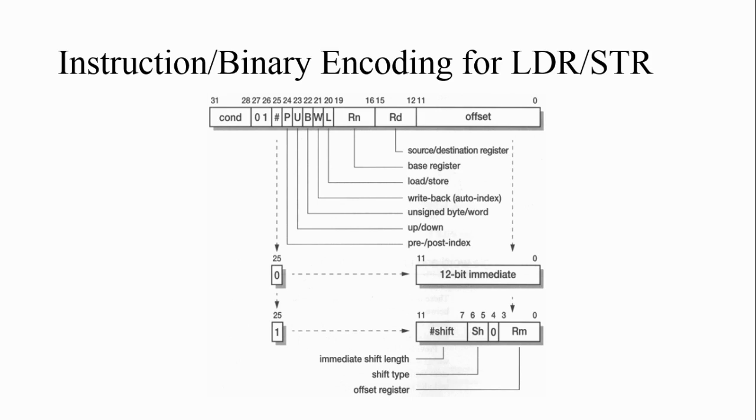So for reading something from memory, you should specify the address, right? And for load and store, you will always have a base address and an offset address. First you give a base address, and from that base address you add some offset to get the next address. Say you want to add 5 numbers: you use a base address and give it to a pointer, and the pointer is incremented to the next location. That incrementing to the next location is known as the offset, and the base address remains the same.